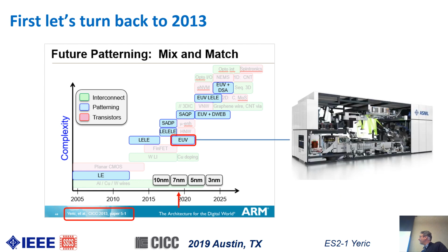As it turns out, EUV did finally make it. And EUV for a limited amount in 7 nanometers and then also in 5 nanometers is actually coming to help this problem, right? We can get back to some single pattern layers, get the cost down, what have you. If you have $100 million per tool. So there, on the design side of things, EUV helps. From the fab perspective, it's an economic issue. You've got to build bigger fabs and put more wafers through there.